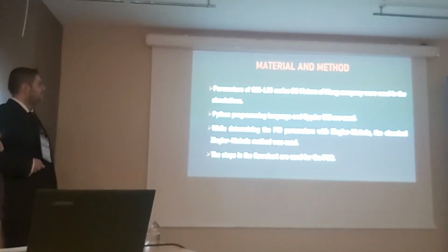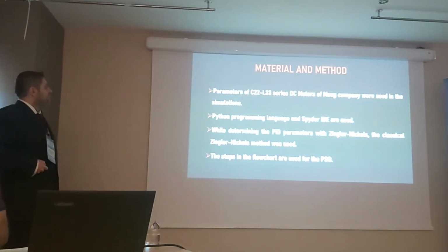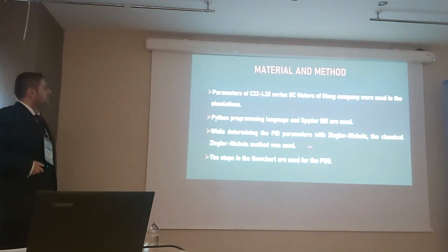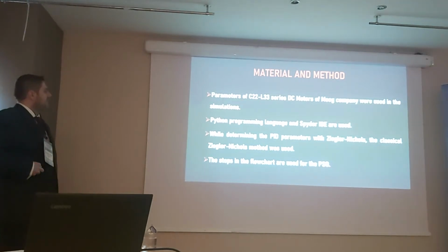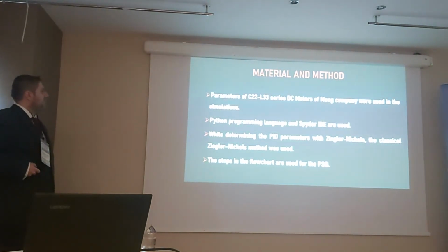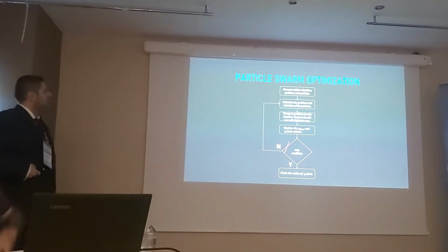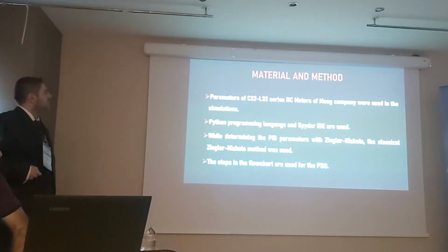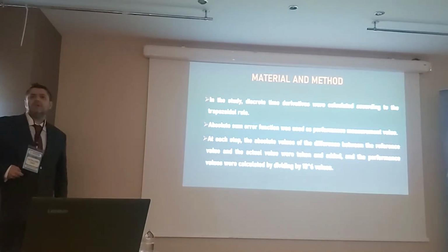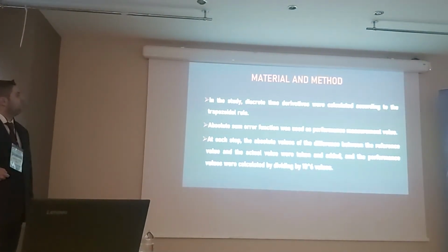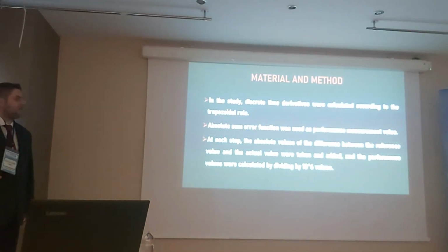We didn't use MATLAB. For Ziegler-Nichols, we used the classical Ziegler-Nichols method, and for particle swarm optimization, we have used this flow chart. For simulation, we have used the trapezoidal rule for differentiation and integral.